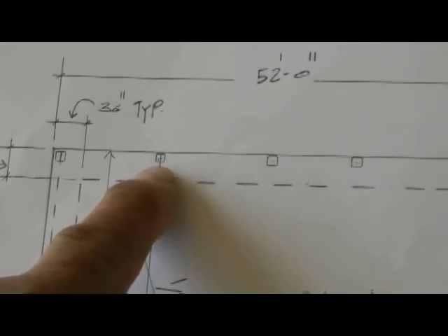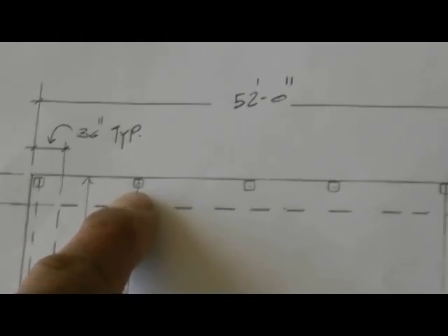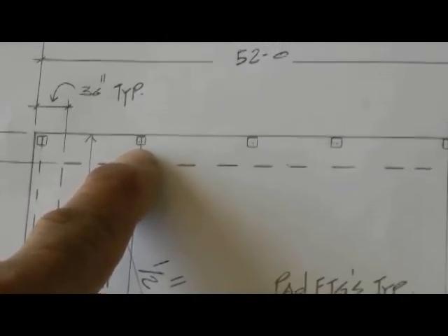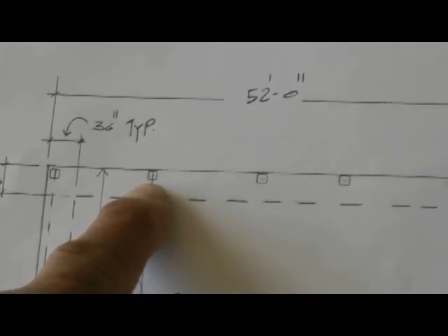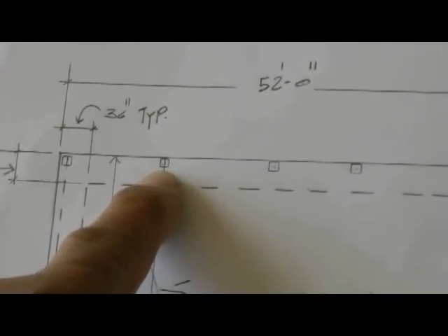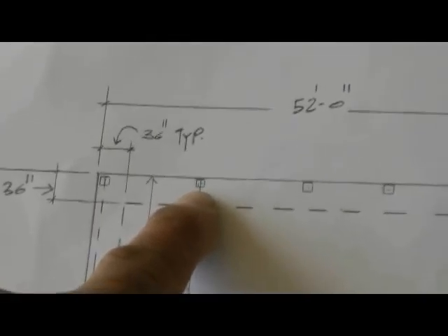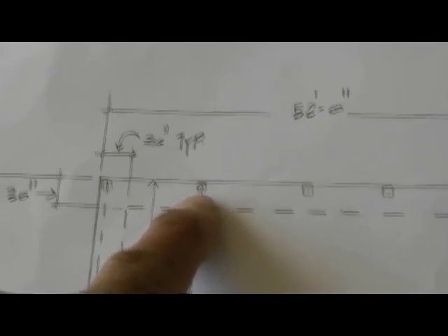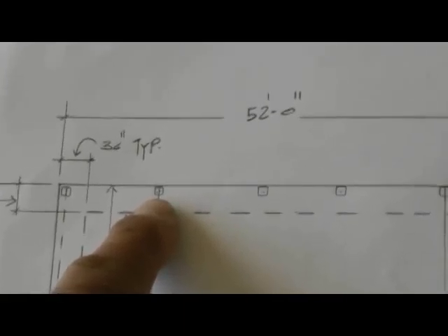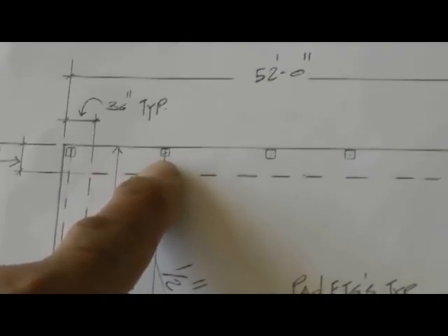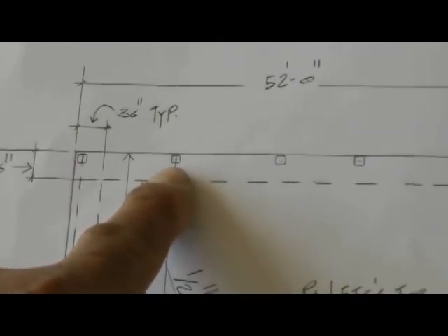Well, I talked to Scott, who's been down there several times, and he spoke with David Eastman, and Eastman said that what Nicaragua does for any sort of structural load path or post is they take C-channels, probably about 2 inches wide, maybe 3 inches long, 2 inches thick, 3 inches wide, maybe a wall thickness of about 3/16 or maybe an 1/8 inch thick, and they seam weld them down the whole length of the C-channels. And they come in lengths of 18 meters, which calculates out to 59 feet, American feet.